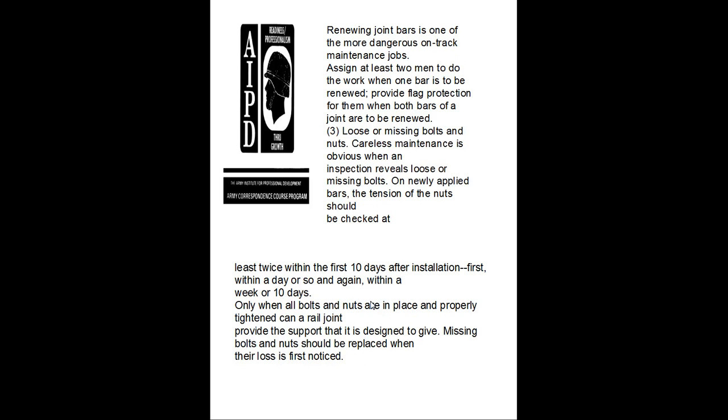Renewing a joint bar is one of the more dangerous on-the-track maintenance jobs. Assign at least two men to do the work when one bar is to be renewed, and provide flag protection when both bars of a joint are to be renewed.